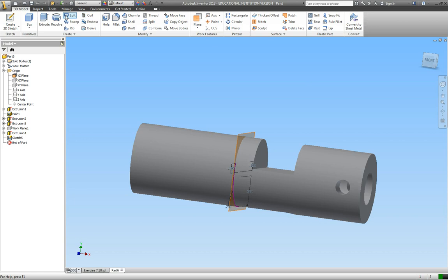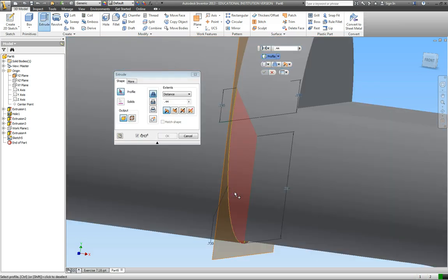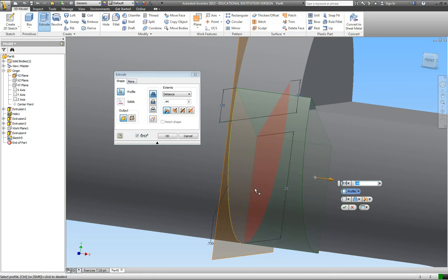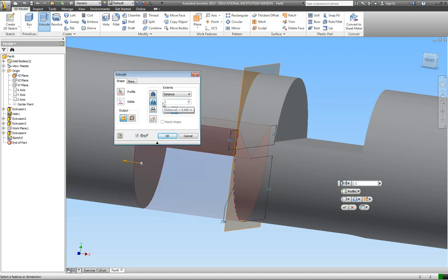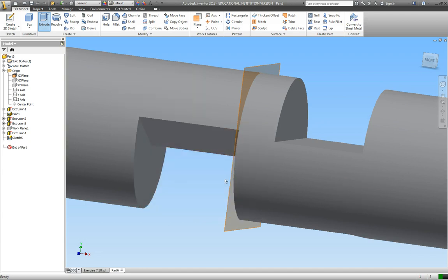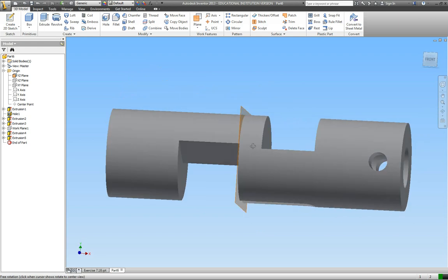So at this point, I just want to extrude, and in my case, since I've got that line running through the middle, I've got to select two different areas. Okay, now it's going the wrong direction. It needs to go the other direction. Plus, it needs to be cut. So let me select cut. Now it's going the right direction, and this needs to be cut by a distance of 1. So select OK. And now you can see that triangular portion created.